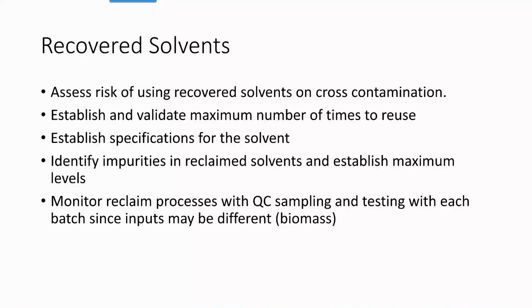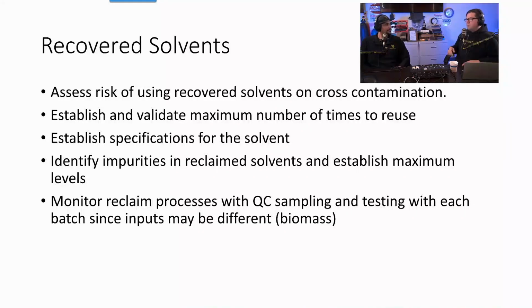Okay, identify impurities and reclaim solvents, establish maximum levels. So you take a solvent in and you extract it, right? What are the impurities that come out? So you're distilling it. Great, that's wonderful. But guess what? Anybody who's ever done this before, you get stuff that co-distills all the time. You just do. And then what do you do with that? Because it's got impurities in it, you have to establish the maximum levels. You have to understand what the impurities are.